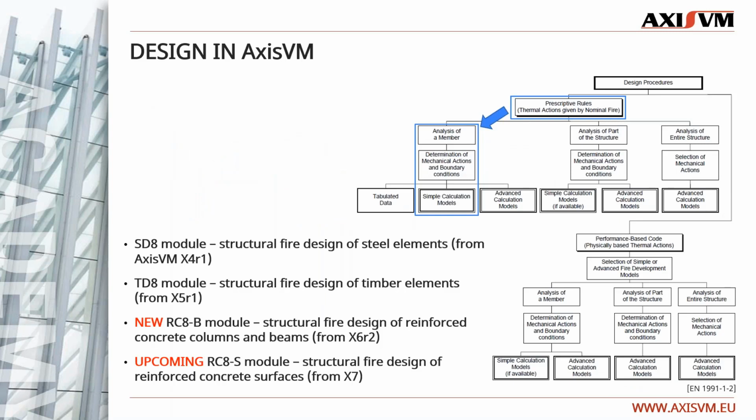A few words about fire design in AxisVM. It is important to know that fire design in AxisVM is based on prescriptive rules according to the standards and design codes, using fire curves and simple calculation models. It is also important that we developed our modules using member analysis. It is an approximation giving the opportunity to analyze only one member of the structure at a time. So we consider an isolated member and perform our calculation on that specific member, and we continue with another one.